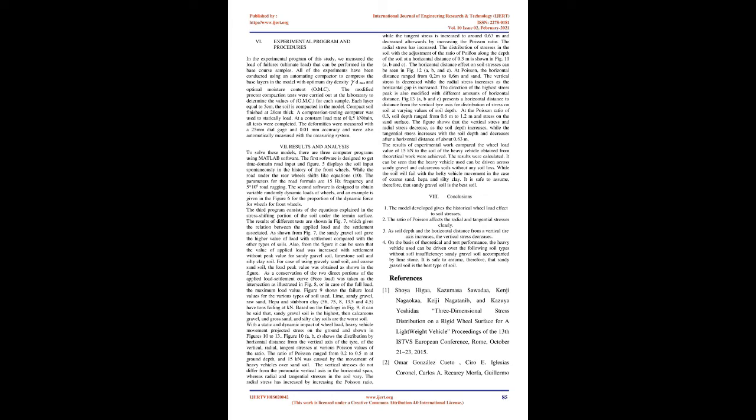It is represented by the steady state of the vehicle, so that because of the static deflection of the suspension components, the effect of gravity on the masses can be neglected in the forces. The 8 degrees of freedom in the model represent the bounce movements of the driver seat, x DS, and the 4 road wheels. Inputs to the model take the form of wheel displacements generated by the vehicle traversing a ground profile. These inputs are not independent, so that a rear wheel input is simply a delayed version of a front wheel input, and near side and off side inputs may be correlated by an amount dependent on their distance apart.